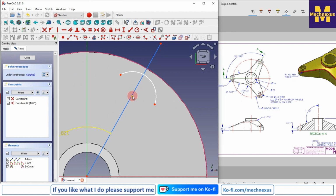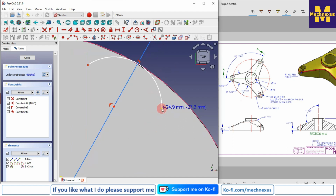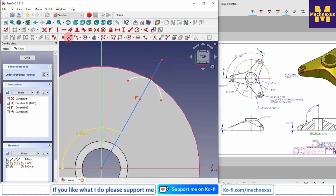Now I will make a coincident relation, and now I will add a tangent, move it, and now I will draw the two lines, and the angle given is 22 degrees.